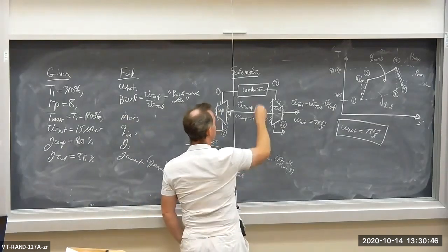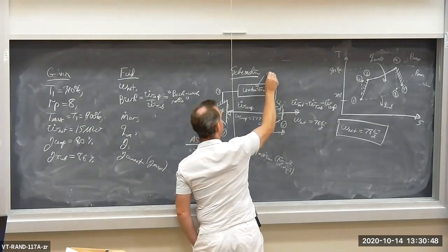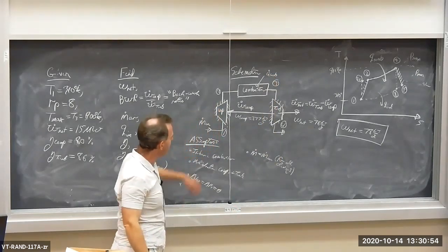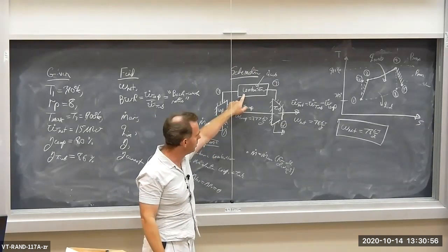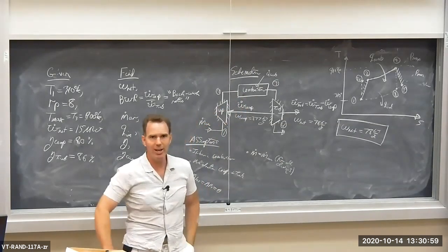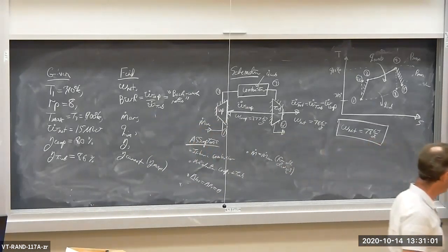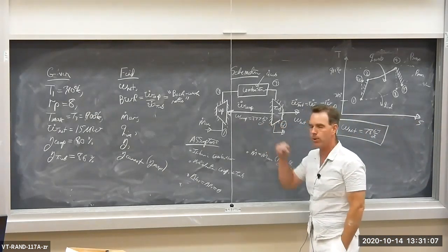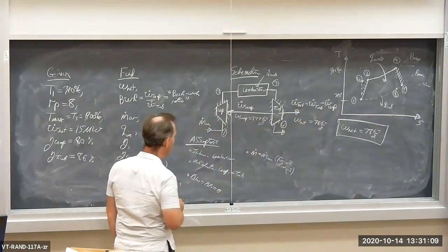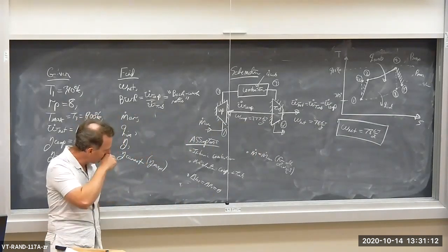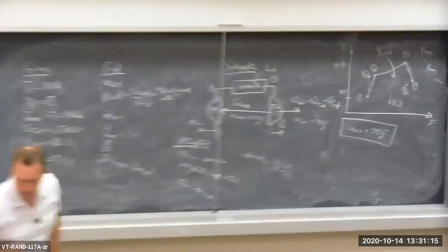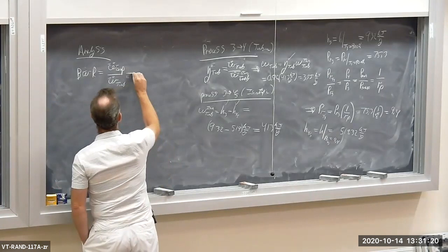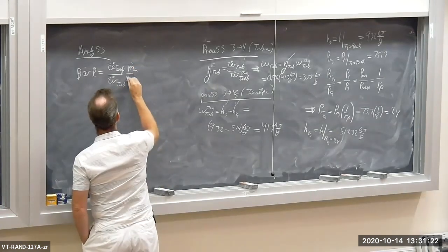The reason is because we are adding fuel and therefore heat, Q dot combustor. We're actually adding fuel into the combustor, not very much. By mass, maybe 1 or 2% of the airflow. We're adding a little bit of fuel and we're burning it. So the mass flow rate through the turbine is a little bit larger than through the compressor, but we're not worried about that. We're going to assume the mass flow rates are constant. Okay? So I'm going to divide top and bottom by m dot air.